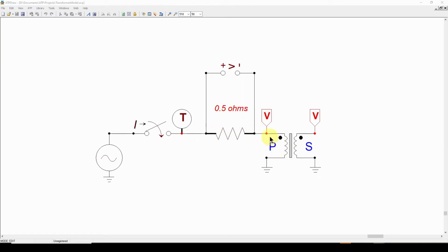And we're also going to be measuring, like I mentioned, RMS voltage across this primary winding and also RMS current into the primary winding. And we're going to be using 2 multimeters for that. So when you look at all the bench stuff, it's basically just this.